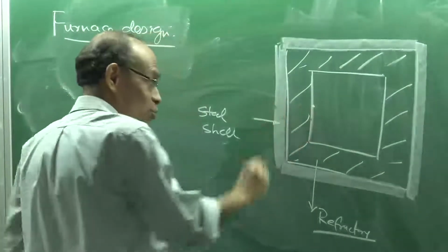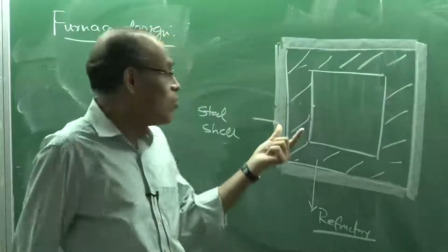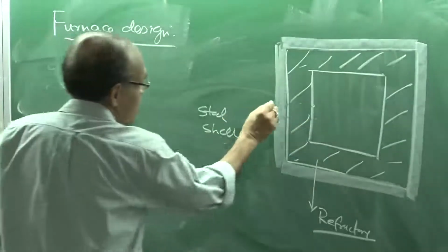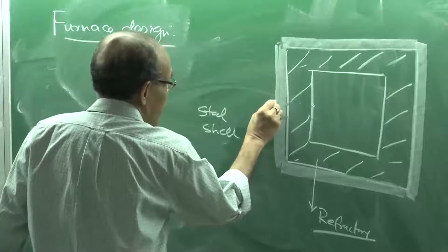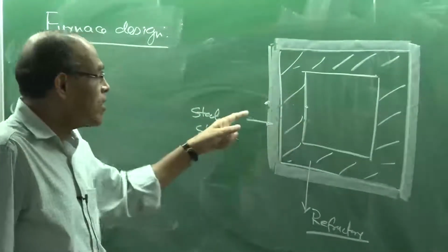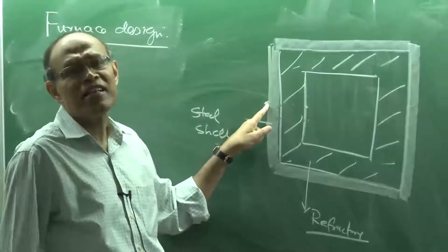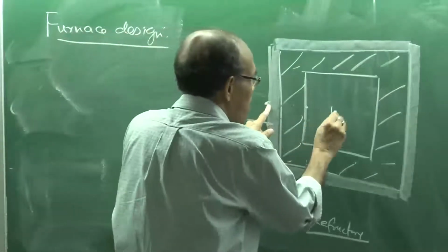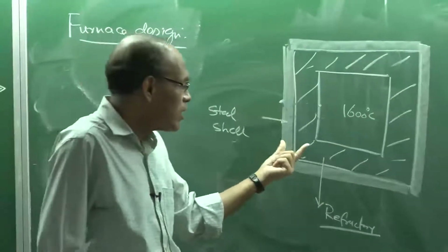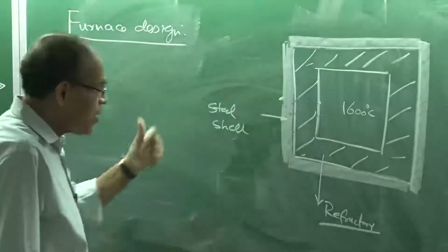The heat flows purely by conduction. So all that we have learned in conduction is going to be applicable: the heat flow, thermal resistance, and certain fundamentals like convective plus radiative heat transfer from the surface, etc. All these would be needed if you tell me that you want a temperature no more than 100 degrees centigrade when I operate at a maximum temperature of 1600 degrees centigrade. You tell me what the thickness of the bricks should be and how the bricks are going to be laid up.